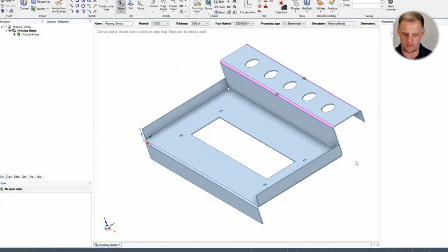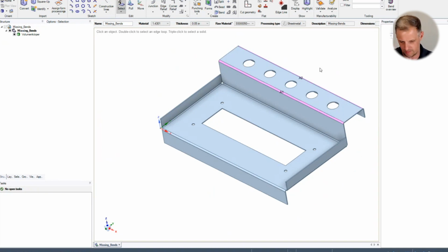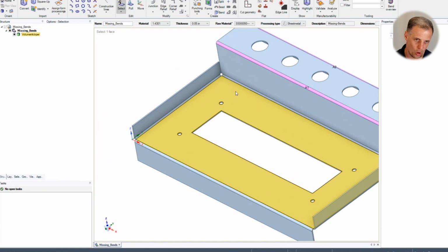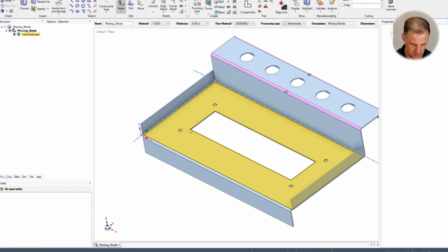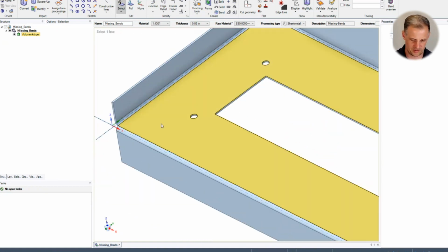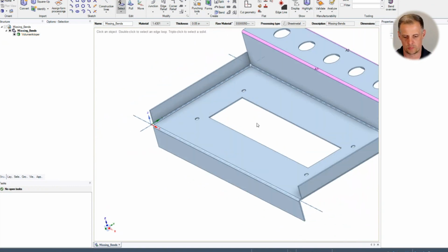And as you can maybe already see, and this is what we learned from our first part, some bends are recognized automatically by Boost. So this is why they are magenta, and there is a letter and a number. That always means they are fully assigned. But also here we have some bends which are not converted automatically during the import process of TruTops Boost.